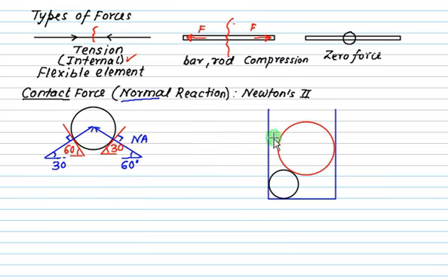In this figure I have given one hollow cylindrical shell which is open on the top, and one cylinder is here on the bottom, and this cylinder is in contact with the larger cylinder. So now how many contact points do we have? We have a normal reaction on this plane. Let's call it A. One normal reaction here is B. One normal reaction here is C. This one, ABC, is the same as this one. So when you want to show this, you can show it like this. So this is Na, always perpendicular to the plane of contact. One is this, that equals NB, and one is this, that equals NC.